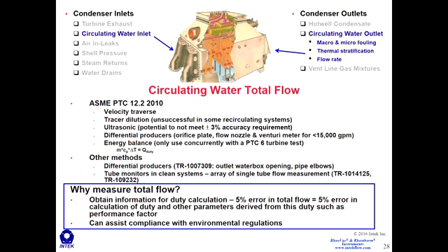There's another method. Single tube meters can be used in clean systems. These are meters that get attached to individual tubes, so you would install an array of these on the condenser to get a flow rate. They have the potential to foul over time, but there are other uses for these single tube meters, and it's a method for getting a flow rate that might be used to calibrate a differential producer. And we've used this several times.